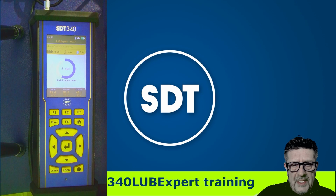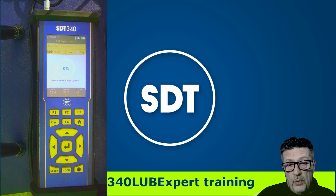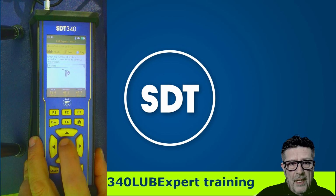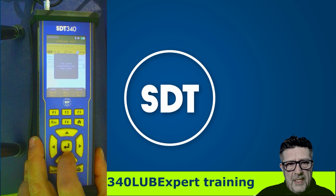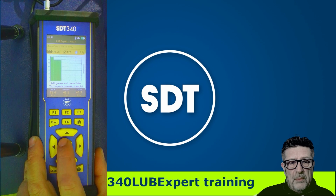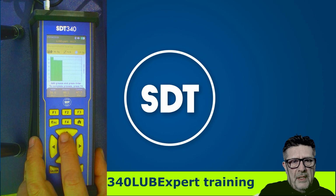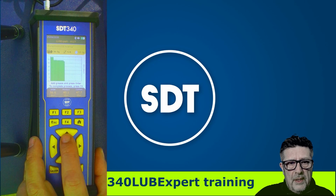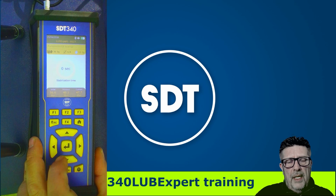Below the graph, I can see initial, previous, and current measurement. So you always see in the numeric expression where you started from. Okay, I added 4 shots, please. I'm acknowledging that. Press enter. This is my third measurement. And the floating bars are going to start to appear immediately. Now I will add another 3 shots of grease. You can see the change. And press enter.